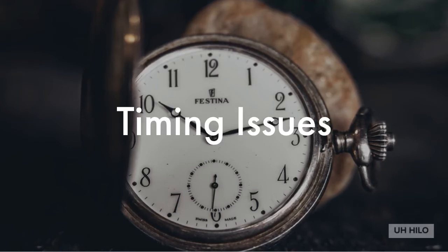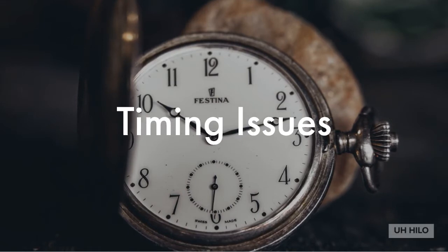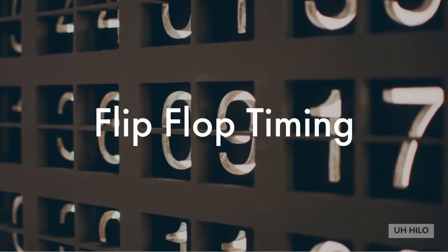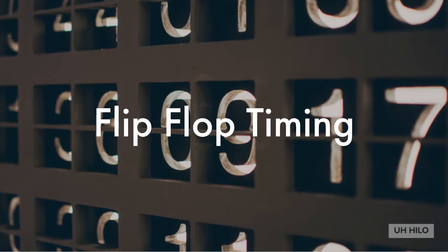Sequential circuits rely on timing, and timing can be a really tricky issue. We'll look at some of the different timing issues and pitfalls that can happen with sequential circuits. To determine how small we can make the clock period, we need to determine the longest delay from the triggering edge of the clock to the next triggering edge. These delays are measured on all such paths in the circuits down which the changing signals propagate.